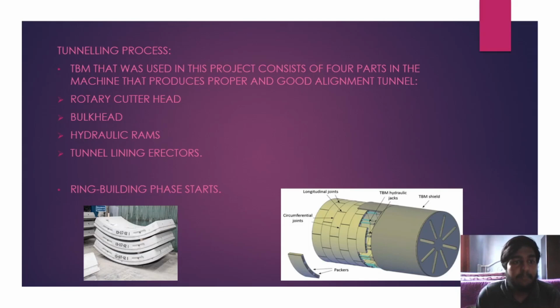So next part is the bulkhead, the portion of the machine where the precious bentonite slurry shield is formed. This is the main part where the stability of the TBM and the surroundings is maintained, preventing the formation from collapsing due to groundwater drawdown that would cause sinkholes.